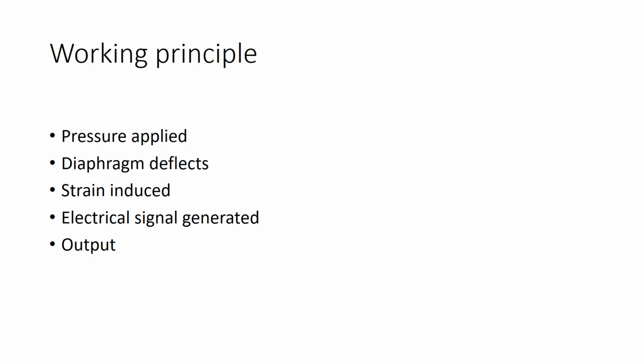Here, first, whenever the pressure difference is created, the diaphragm will deflect. This we know what is meant by diaphragm that we discussed already. This diaphragm movement is transferred to the armature. This armature transmits the moment of force from one component to another. Here the armature produces strain on the strain gauges. This strain gauge changes its electrical resistance.